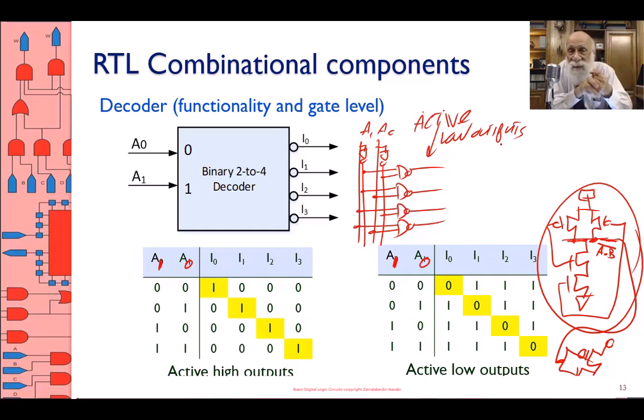Say, this is a decoder with active low outputs. And then put a symbol there to indicate that this is a decoder with active low outputs. Okay? Because nobody's going to look inside your decoder. You have to clearly tell the person using this circuit that it's a decoder with active low outputs, and therefore you put bubbles on the outputs to indicate that this is active low.